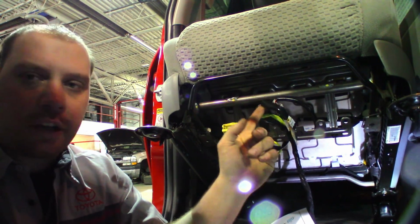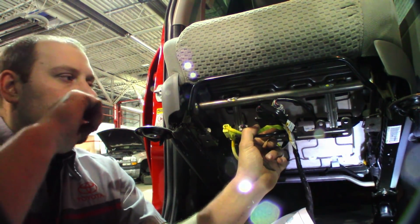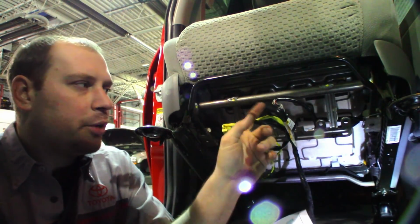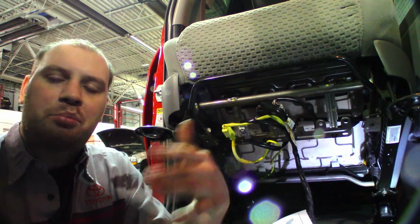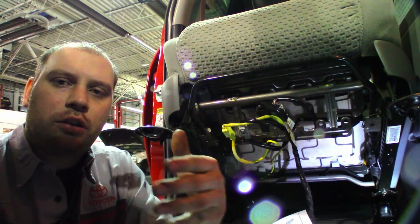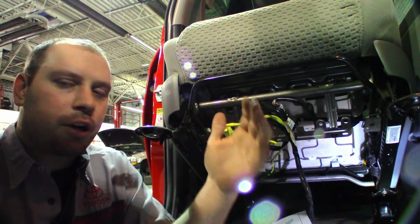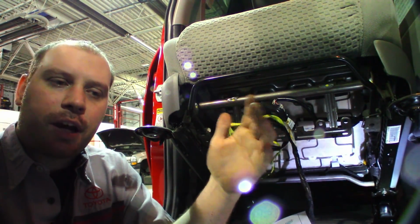This black box here under your passenger front seat is your occupant detection module. First thing I'm going to check when I have no communication is my power and grounds. Now, when I made a Chevy map light video, I actually back probed these terminals, because that's usually how I load circuits. But it was brought up to me by a guy named Brian Collada, who's trained by Tex, who's a really smart guy, that you're not 100% sure if that circuit is actually operational at a module. So it's always best to substitute loads. And after speaking to him, I actually agree with him.